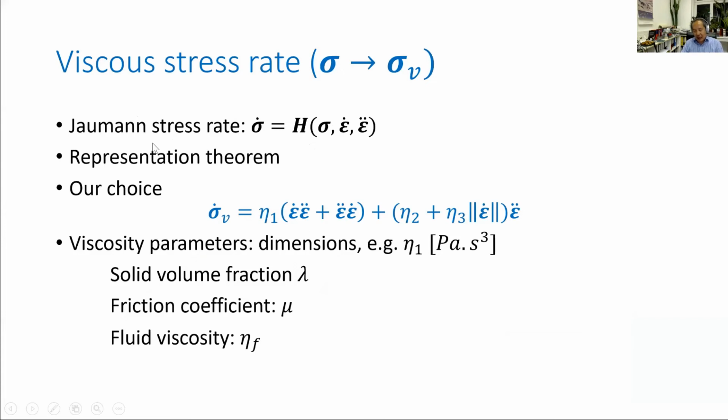If you look at continuum mechanics, if you consider tensor functions, you consider only polynomials, and there you have some candidates, and here's our choice. So there is no big theory, no microscopic considerations. The only thing here, you won't have a normal stress effect. So it means during the shearing, you should have normal stress. And this is a possible expression. Others are also possible. These parameters a1, a2, a3 are the viscosity parameters, right?